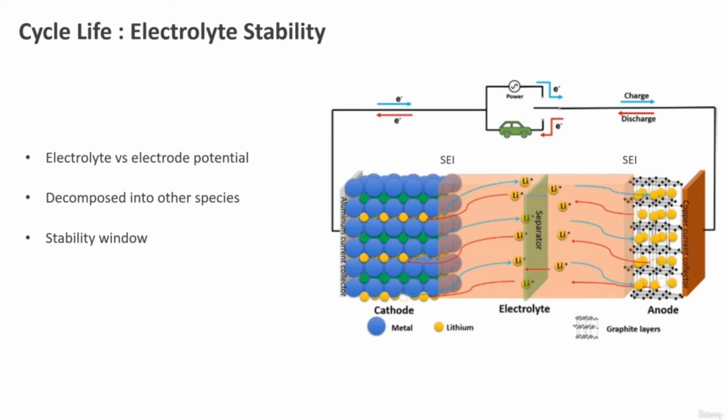If the electrolyte is oxidized or reduced by these potentials, this implies that the electrolyte is decomposed into another species, which may be insoluble in the electrolyte, often bonding lithium in such a way that it is not active anymore. As a consequence, some capacity is irreversibly lost and part of the electrolyte is decomposed, which are major factors that cause a finite battery cycle life.